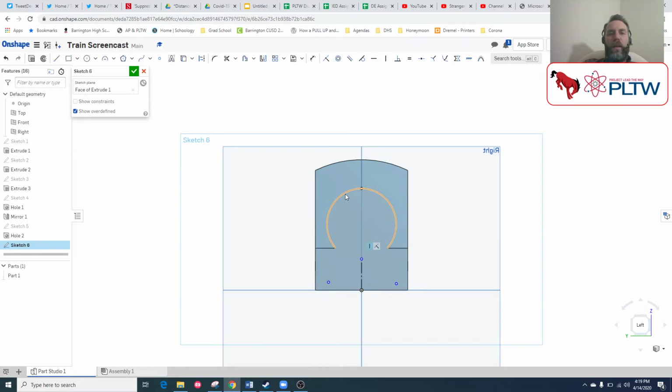So let's put in our height dimensions first. Well, actually, no, let's make these bottom 2 horizontal of each other, so I only have to dimension them one time. And the reason why I put in that center line was so that I could use the symmetric command and make it such that those two share the same relationship about that center line, so that when I drag one, I get both of them to move. So I drag one, they both move.